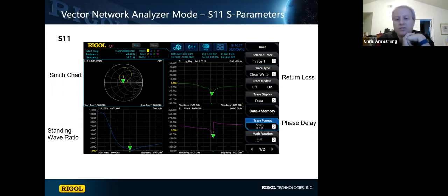I just put a couple of examples here that we could talk through. Because of the technology built into the box, the tracking generator with the built-in differential coupler allows you to look at a couple of classic S parameters in a network analyzer mode. So you've got S11 and S21 measurements, and then we'll look at the reflection of our distance to fault measurements.